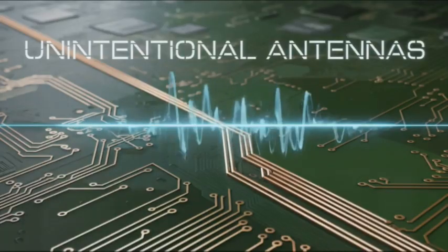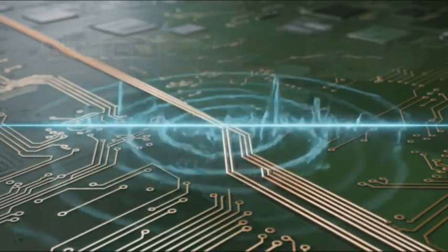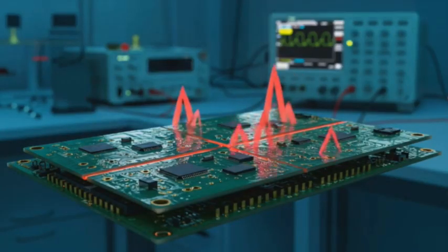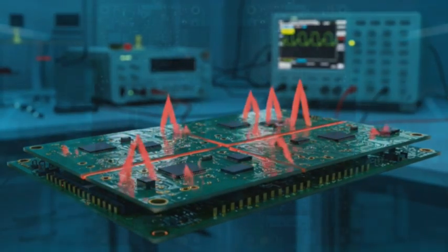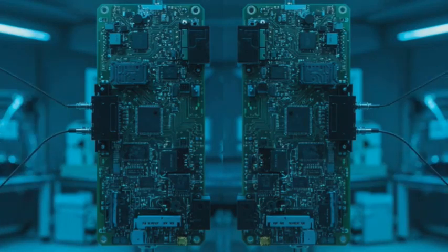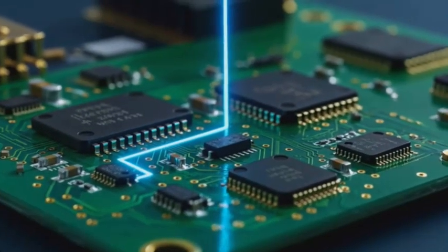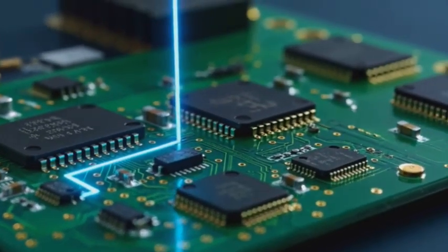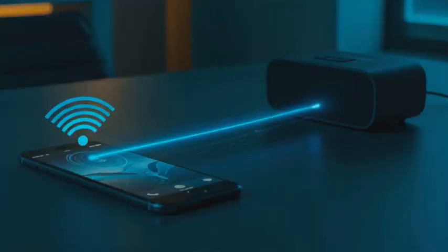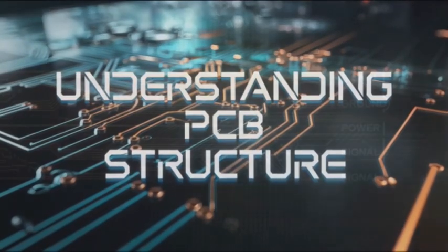A significant EMC challenge arises when PCB traces unintentionally become antennas, especially if there's a split in the ground plane. Antenna reciprocity means structures good at transmitting also excel at receiving, causing both emissions and susceptibility issues. Intentionally designed antennas, such as Bluetooth antennas, often use this same principle deliberately. Understanding PCB structure is fundamental.